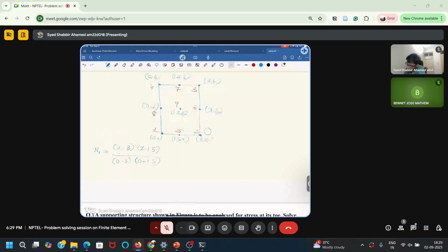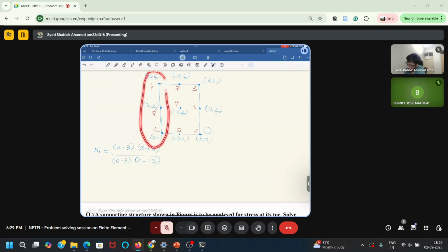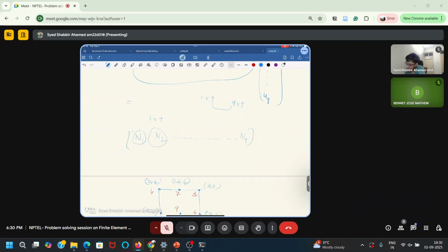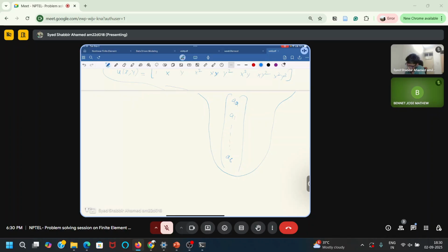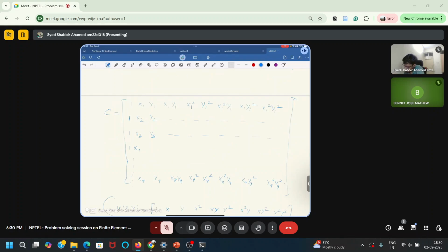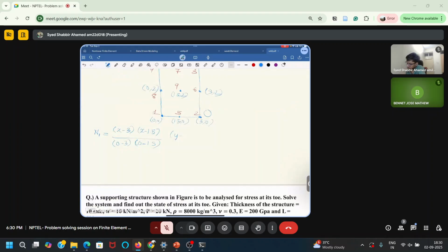Into, now you take this line also, and now you write only the shape function, assuming that this is 1D in y. So a line is one dimensional in y, right? I can just take y minus, except this, I have to take two. Yeah, Lagrange interpolation, that's what we are doing, right? Instead of taking this cumbersome approach of taking the coordinate matrix and doing the inverse, this is kind of a shortcut for doing the Lagrange interpolation.